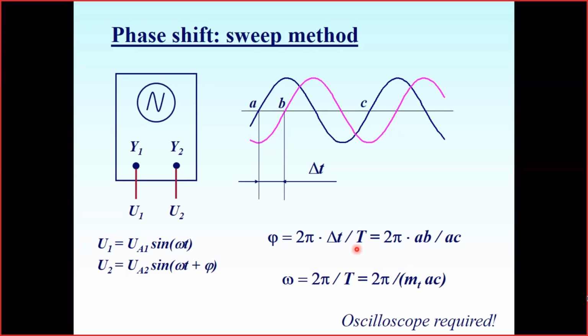One of the simplest ways to estimate a phase shift between two signals is to use an oscilloscope, depict the two waveforms simultaneously on the two-channel scope screen, and measure the time between the points with the same phase. We have to remember one important aspect: which points to select. There are two approaches.